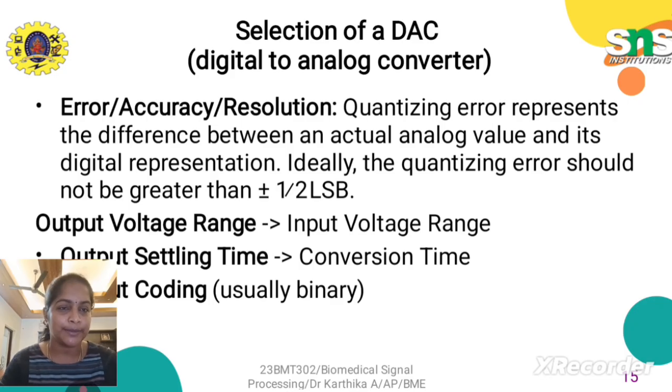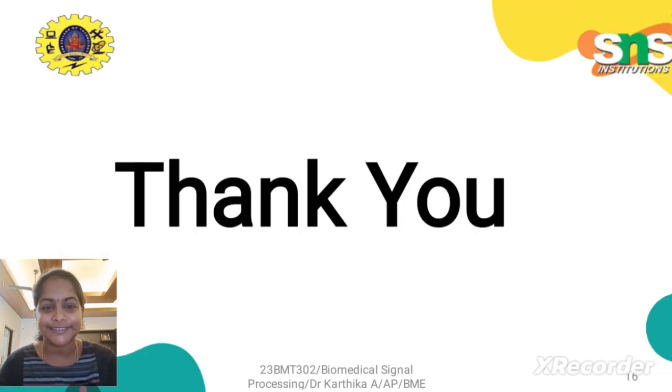And so, when coming to the selection of a DAC, digital to analog converter, we have to predefine error, accuracy, resolution, output voltage range, output settling time, and our output coding part. Usually binary coding is adopted here.